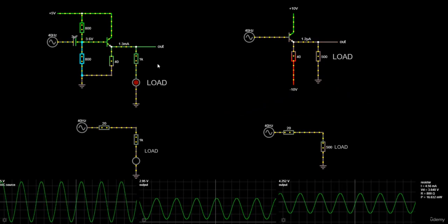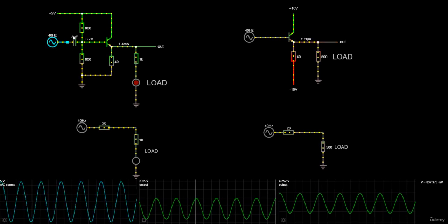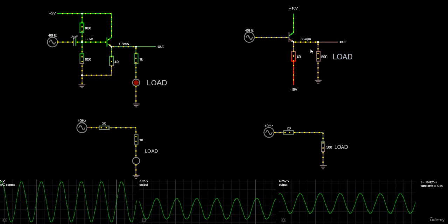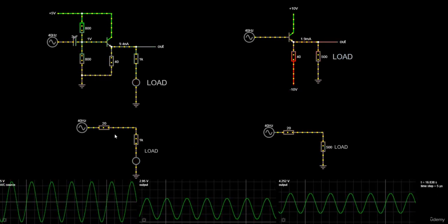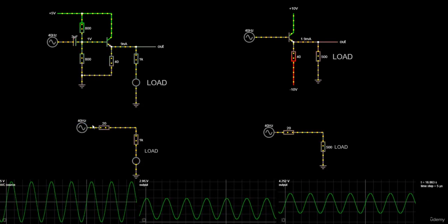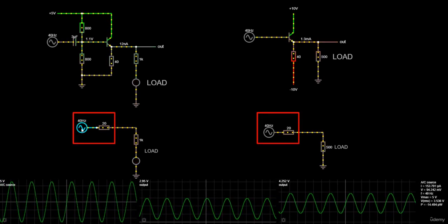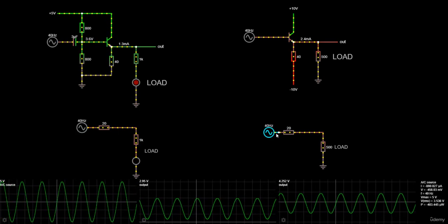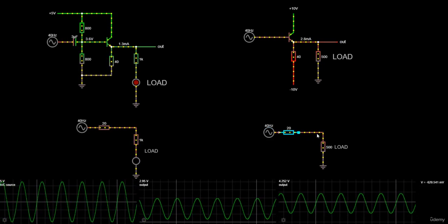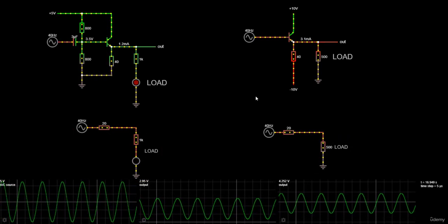In the next course, we will be discussing this input and output impedance thing, so you will understand why I said that a signal that has some internal impedance can now drive a load of comparable or even lower impedance without loss of amplitude. So don't forget that all these signal generators in the real world have some internal impedance, okay? In the simulator, it can be perfectly represented by hooking a resistor in series with the signal generator. The output impedance of a signal generator is small, and you have to take this value into consideration, especially when you connect this part of the circuit to another circuit. And we will see why in the next course.